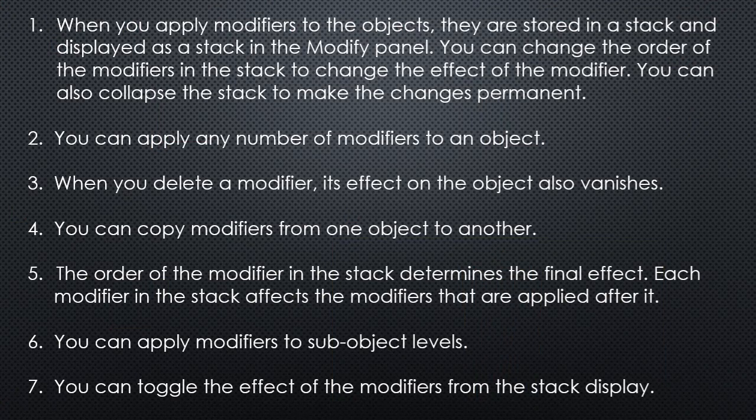Following are some points that you should remember about modifiers. First, when you apply modifiers to the objects, they are stored in a stack and displayed as a stack in the Modify panel. You can change the order of the modifiers in the stack to change the effect of the modifier. You can also collapse the stack to make the changes permanent.